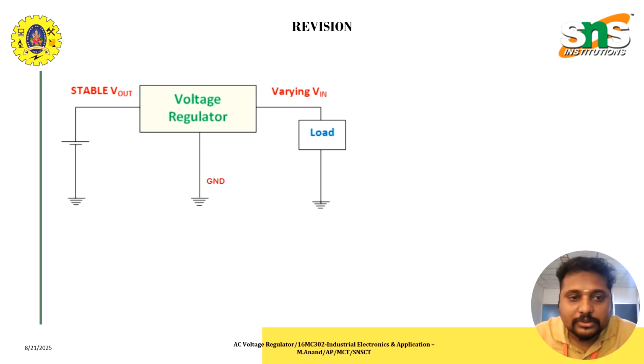For this voltage regulation, we are using the LM78xx series voltage regulator IC to regulate a particular voltage. For example, in 7805, the last two numbers indicate the constant voltage. For 7805, the output will be 5 volts.